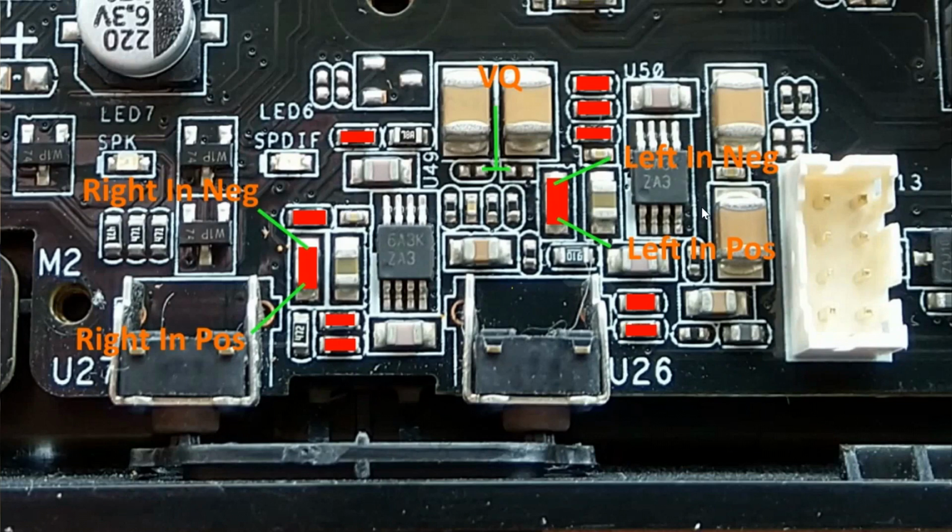So to hook up the new front end, we need to make a few small modifications to the circuit board. I would like all modifications to be reversible, because I don't know if this change is going to have any effect. Maybe it will make the performance worse, and then I would like to return it to original. What I have marked here in red is all the components that have to be removed in order to completely disconnect the original front end from the analog to digital converter. And then we can connect in the new front end using these points I marked here.